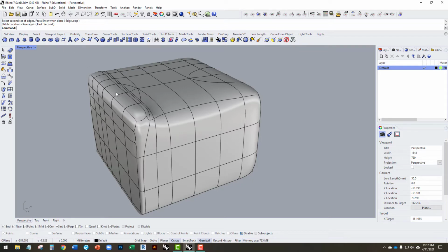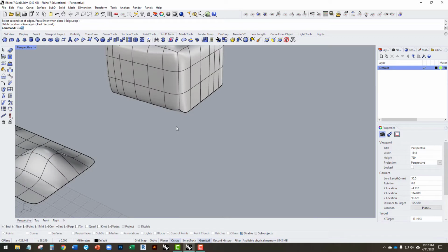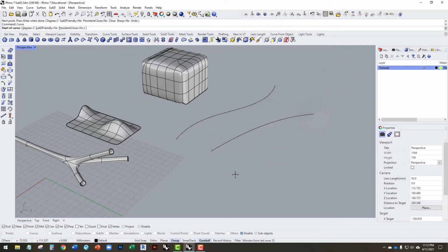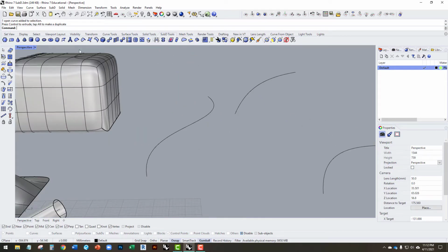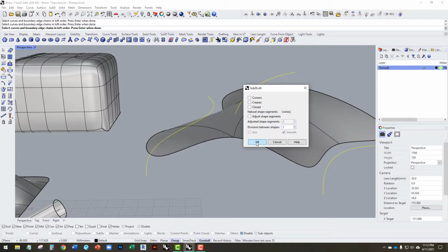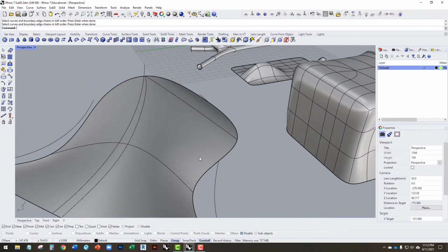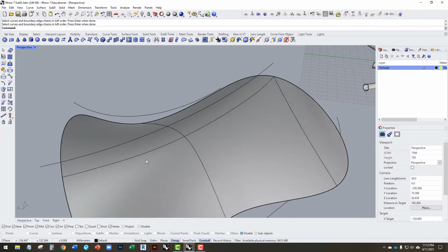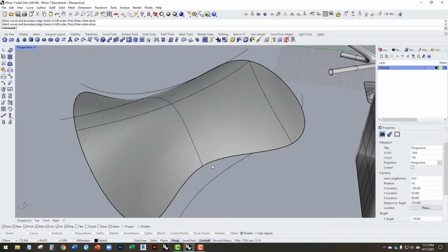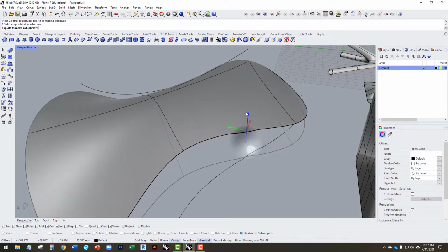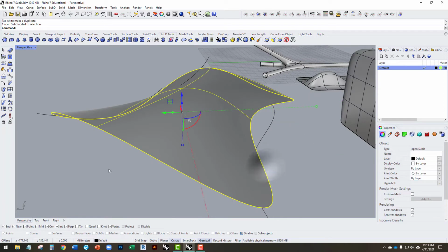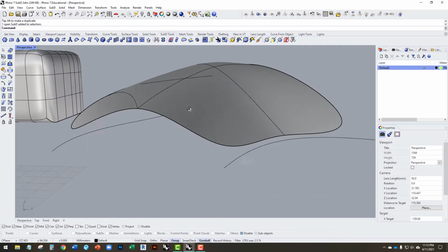So there's also a SubD Loft, so we can start this whole process with curves. So if I just draw some NURBS curves, we can loft these curves together and generate a SubD geometry. So I can loft these, click, enter, and it'll simulate a surface that flows through those three curves. So in the same way, I can shift, control, click, and manipulate each of these faces or edges or vertices. All right, so different ways of generating the SubD geometry.